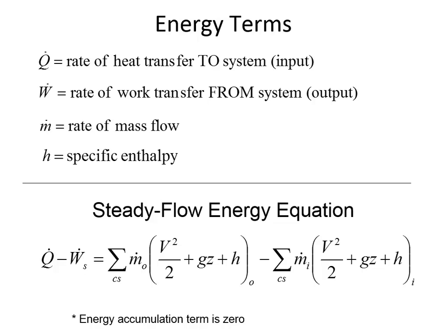In a pipe network, the water temperature actually does increase because of pipe friction. We're talking about how all this electricity has to be used to move water from one place to another. There's pipe friction, and just like if you rub your feet on the ground and then feel your shoe, it's warmed up a little bit, or rub your hands together. The reason why they get warm when you rub them together is because of friction. Friction generates heat, and the same thing is true with flowing fluids, and so it's perfectly appropriate for us to keep track of heat transfer to the system because the energy losses go into heat.